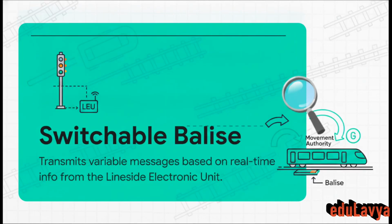This one is highly dynamic. It can transmit variable, changing messages based on real-time info it gets from a device called the Line-Side Electronic Unit, or LEU. You'll typically find a switchable Balise installed near physical signals. Its main job is to hand the passing train an up-to-date movement authority, which is basically a digital green light to proceed, based entirely on the current status of that specific trackside signal or interlocking system.